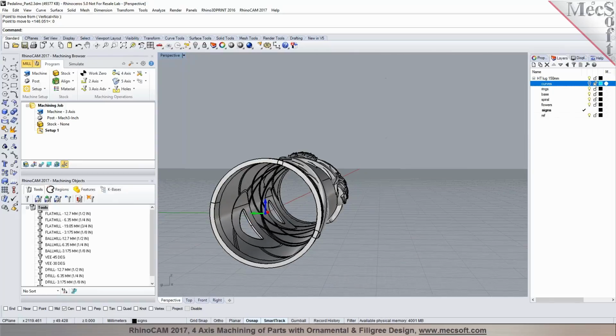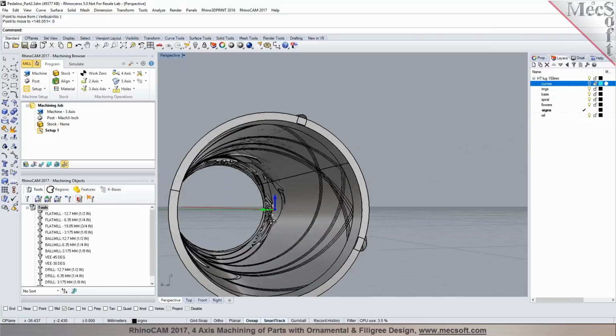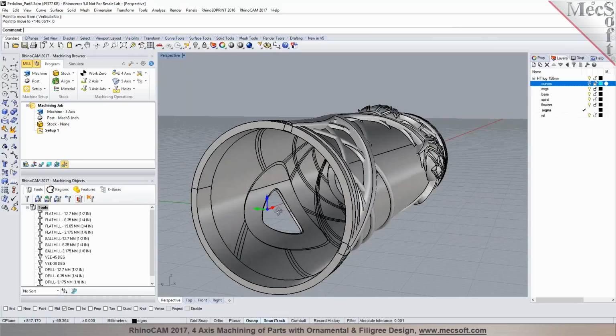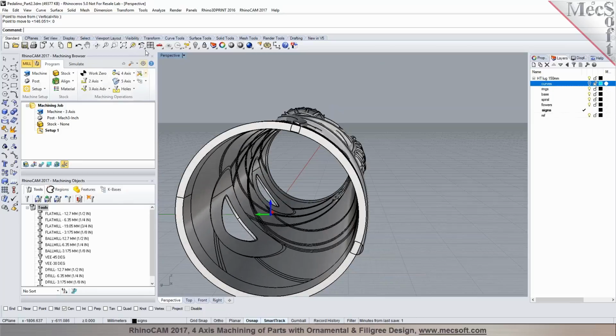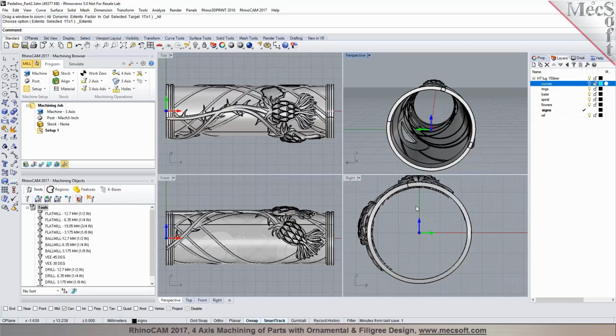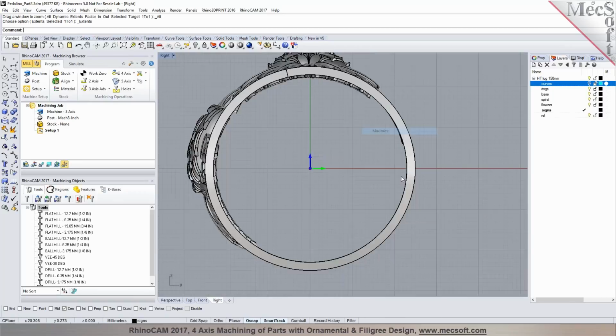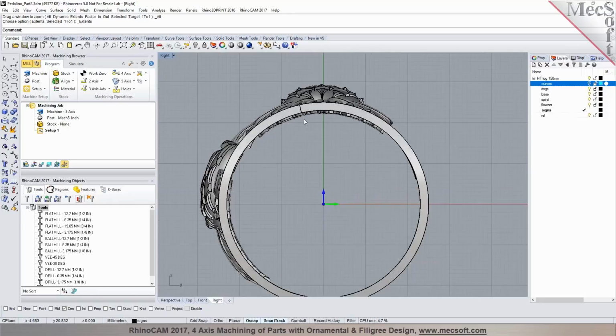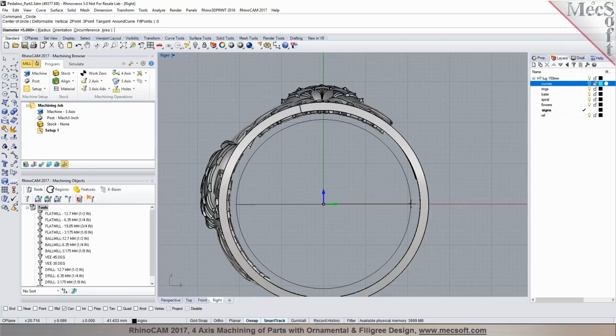That's fine, yeah. Okay. Now I see that there are some hollow cross sections on the part on the inside. So are you going to be working off the tube stock again for this as well? Sorry, what was that? Are you going to be using a stock that is hollowed out like a tube for this part? Yeah. Okay. All right. So what I'm going to do is put in a cylinder, like a catch plane, so that the toolpath doesn't go past a certain area in here. So I'm going to use a circle command in Rhino, and maybe I'll just go in a circle, so that's how far you want the cutter to go into. Okay, that makes sense.